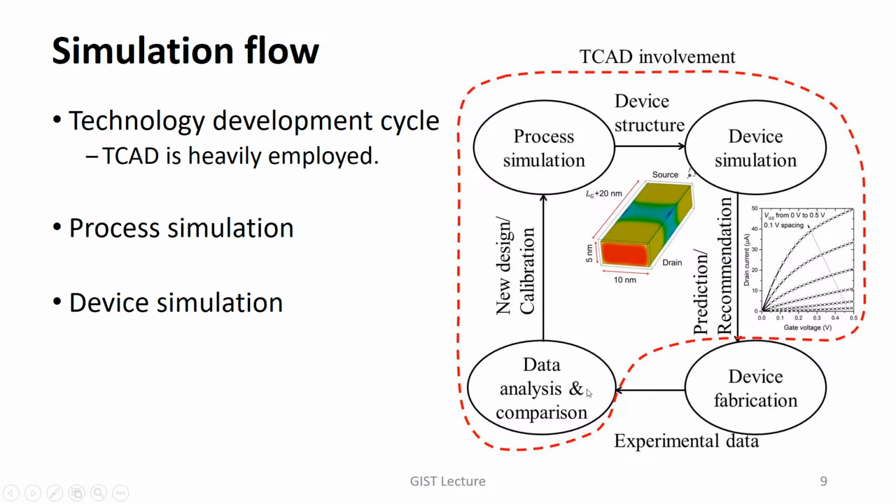From data analysis and comparison with TCAD data, we can find new process options, and the process simulator can give you the structures expected from the new process steps. Then within this device structure, we can perform device simulation and also get certain estimated or predicted values of our device.